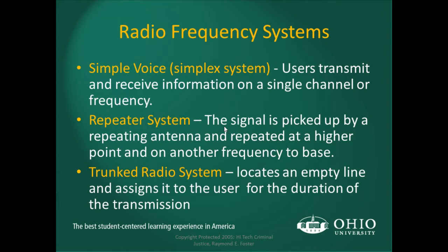For instance, in our system here in Grove City, we have a 5-frequency trunked system. One frequency is always set up for the data, so the data is transmitted across the system to say who's talking on what group, who has hold of what group. The other 4 frequencies handle 4 different simultaneous connections. As I pick up and go to talk, I talk on that particular frequency. It holds that frequency until I'm done, and the next time I key up, I may be on a different frequency. So a trunked radio system allows for a lot of capacity through a small number of frequencies or channels.